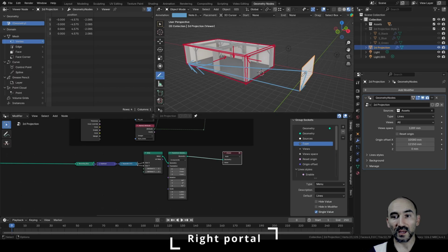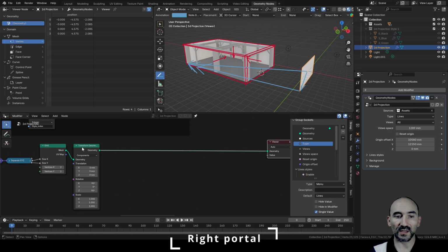So in this way I can add this difference to this point or this entire object, and I will shift the entire object to this point. I could use directly the translation of this transform geometry, but I prefer to divide this problem into smaller problems.